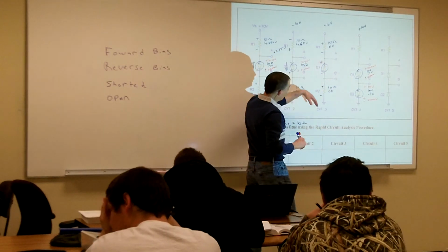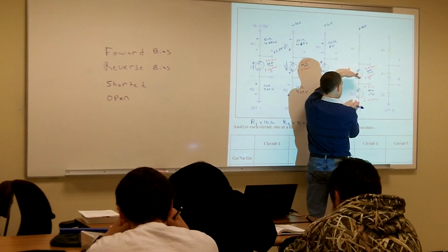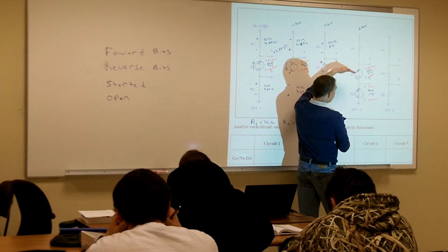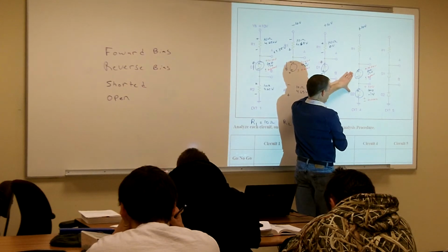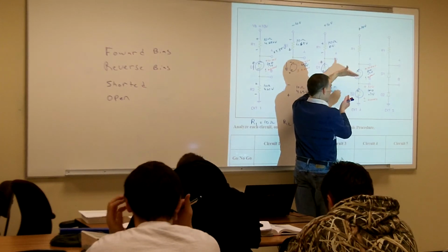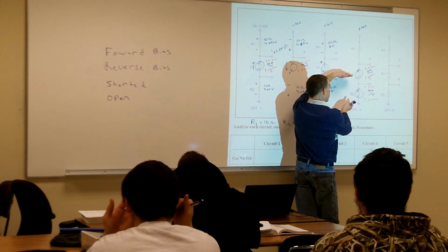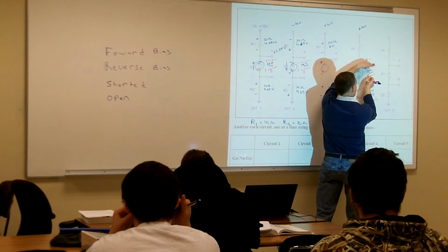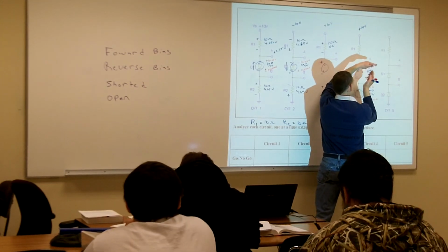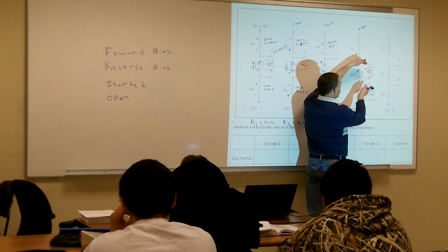Now what can actually happen is that when I first apply power to these diodes, just the way we're analyzing these circuits, they're going to act like an open. So if I put an oscilloscope on there, the minute I applied that voltage to it, I wouldn't get the 0.7 volts right away.